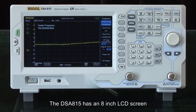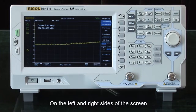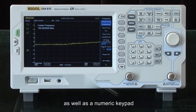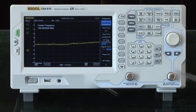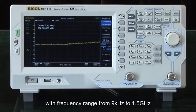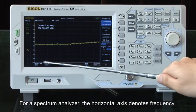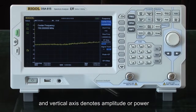The DSA815 has an 8-inch LCD screen with 800 by 480 pixels. On the left and right sides of the screen, we have various buttons, knobs, and a direction button, as well as a numeric keypad. There is also a USB port for accessing external USB drives. The Rigol DSA815 is a spectrum analyzer with frequency range from 9 kHz to 1.5 GHz. For a spectrum analyzer, the horizontal axis denotes frequency and vertical axis denotes amplitude or power.